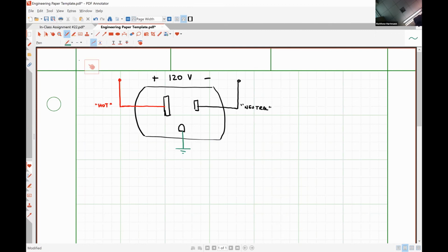Well, this 120 volts right here is not the actual voltage that's generated across the terminals of this, because this would imply that there is 120 volts of DC power being supplied by our receptacles. And power in the United States and most of the civilized world is distributed using alternating current. So instead of 120 volts, what we would actually have is that voltage V of t is, I think it's 169.7, but let me double check. Yep, 169.7 cosine 120 pi t here in the US plus some phase angle theta V volts, where that phase angle depends on when we start measuring things.